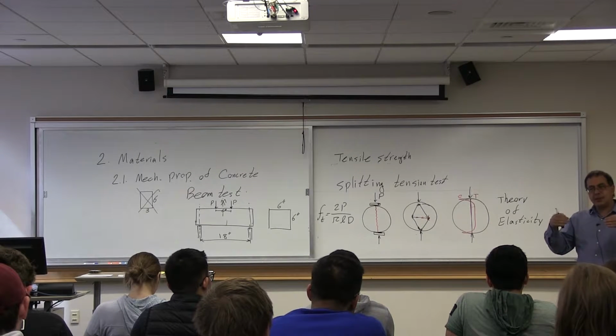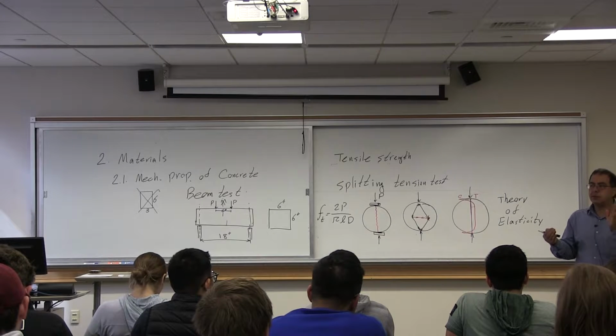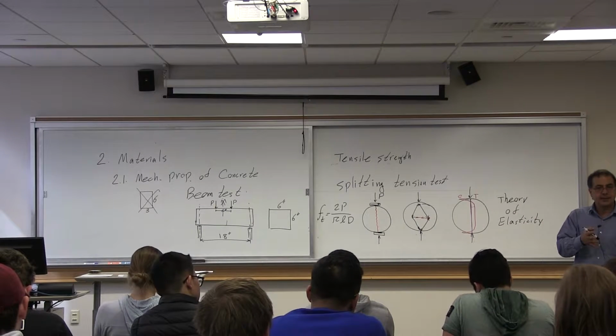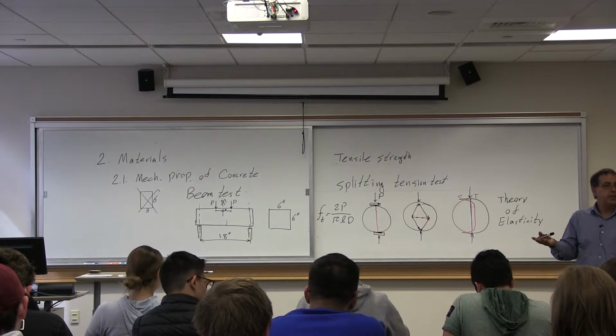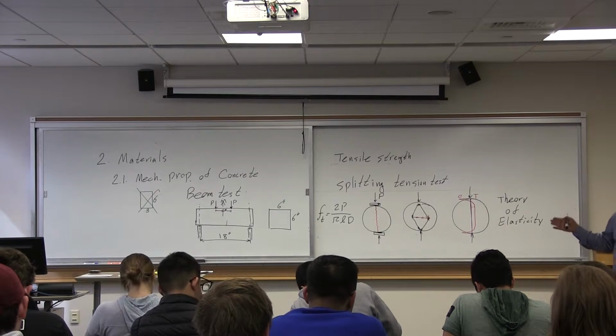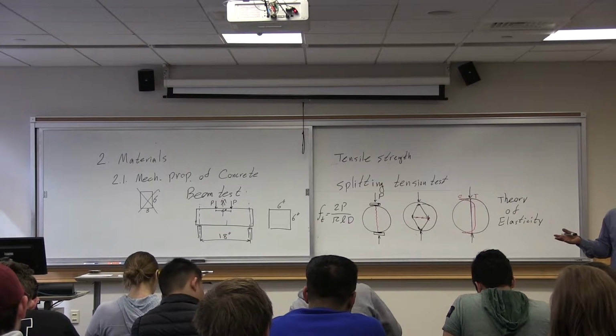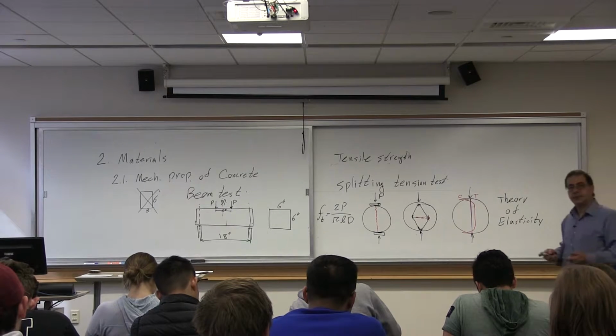So you need to think about it technically. Why does it break? Because of the moment. Where does it break? Where the moment is maximum. Is the moment maximum at midspan? It is, but it's not just the midspan that has maximum moment. It's anywhere in between the two.